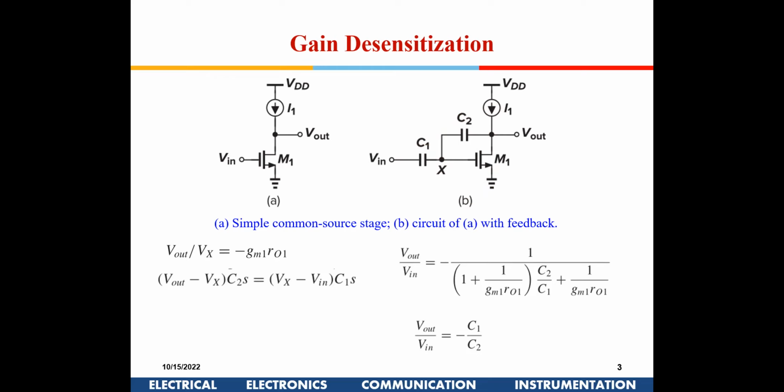Is it okay? Sir, one doubt. You mentioned the capacitance of the MOSFET is lower, and that's why current will move to C2. I didn't understand the relation between the flow of current and the capacitance value. See, it is like a low resistance and a high resistance. This current could go in this branch or this branch, right? So you are considering this a very high impedance? Yes, the impedance is 1 by C, so small capacitance means high impedance. So some negligible current is going here, and most of the current is going to the top.